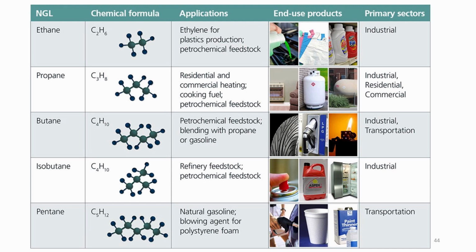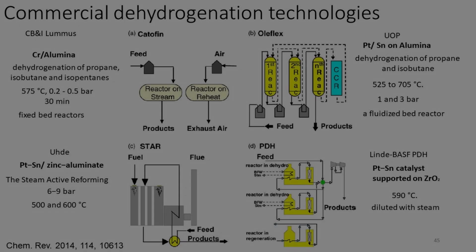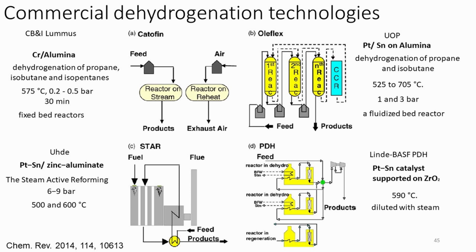An important aspect in dehydrogenation entails approaching equilibrium or near-equilibrium conversion while minimizing side reactions and coke formation. Commercial processes for the catalytic dehydrogenation of propane and butane attain per-pass conversion in the range of 30–60%, while the catalytic dehydrogenation of higher hydrocarbons, C10 to C14 paraffins, typically operates at a conversion level around 10–20%. Let's consider commercial dehydrogenation technologies.